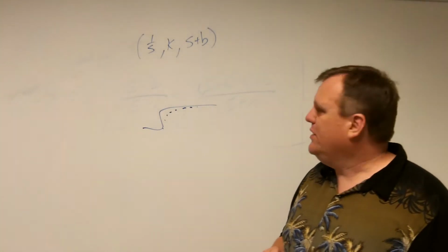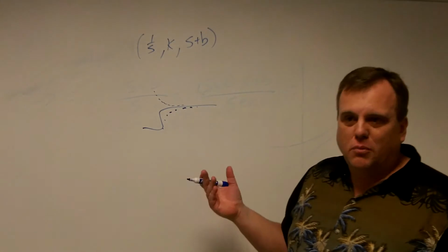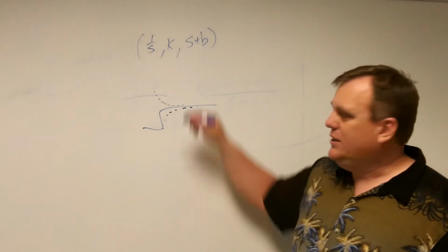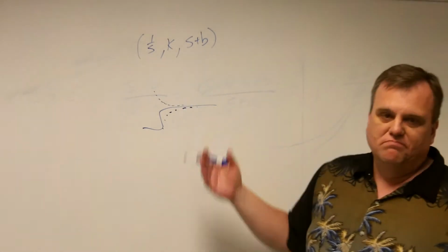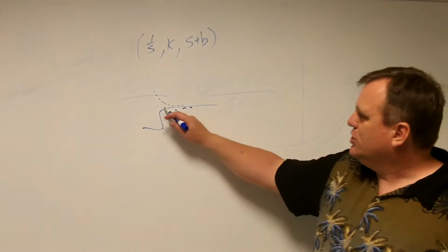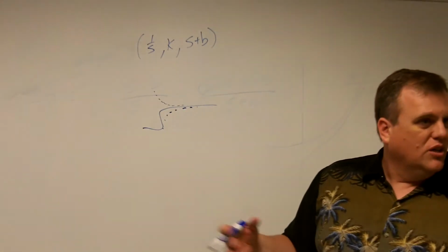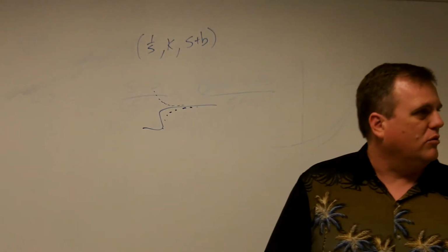So it's no big deal. If it adds onto it, then you're doing this. So the plus or minus the exponential just tells you, are you coming from the under or the top? Am I decaying down to a bias or powering up to a bias? Right? And then we just call that the asymptotic behavior because the step function lasts forever. To realize pretty much anything else you do will reduce down to the same type of behavior.